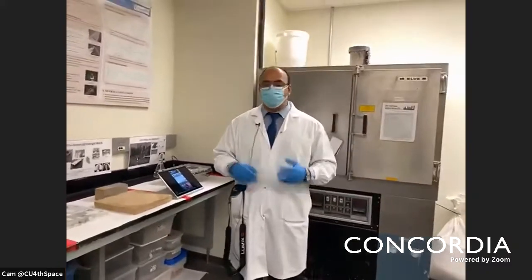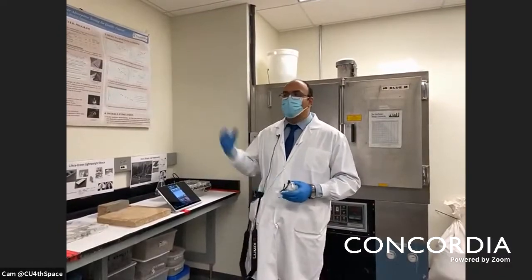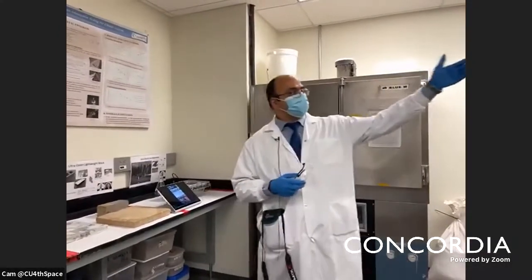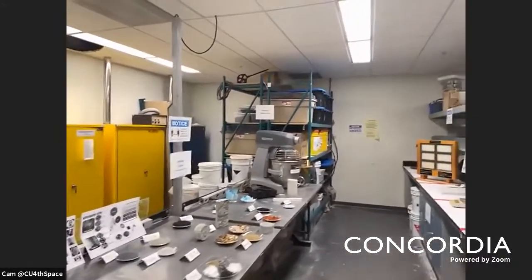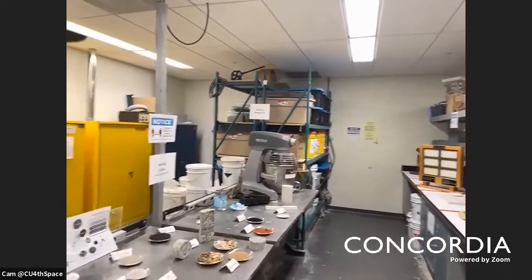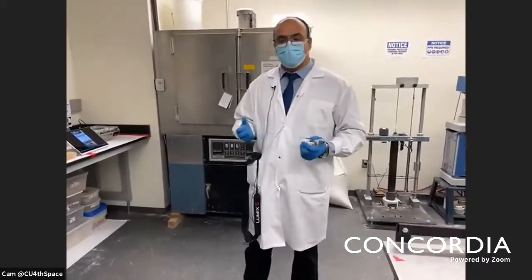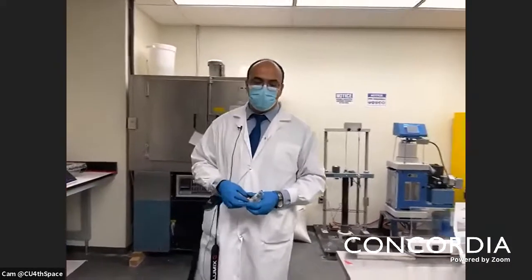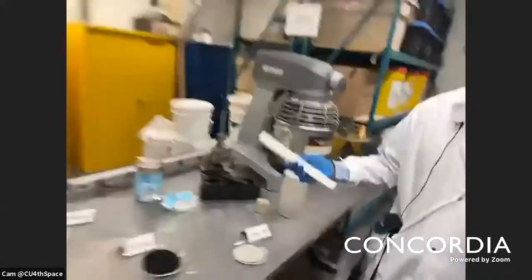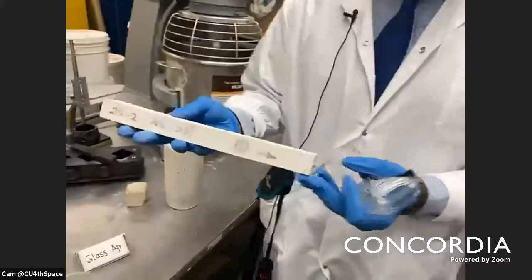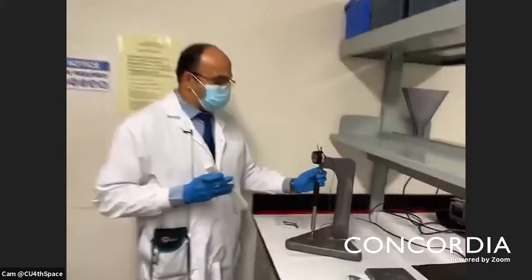Now, if we would like to talk about exactly what steps we follow when we start with our material. When we get our material, as you can see in the back, we start storing it into different categories. We have the aggregate, we have the cement, we have the fiber, we have the admixtures. Then we start thinking about what will be a useful application for our material. Then we have experimental design, start making some trial batches, and fabricate small samples like that. This is a small sample. We use it for measuring shrinkage here. So we put it down here.